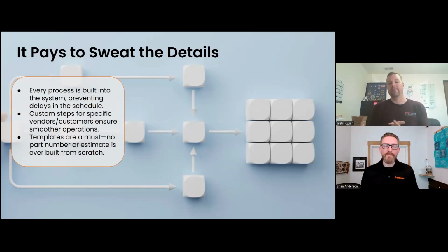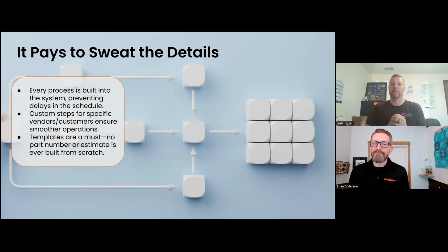But what that created for us was that work stoppage. So now we have those custom steps for this customer that right after we receive material, which is a line item on every work order, it's check for ultrasonic inspection cert on everything. And there's a big note: do not proceed past this step until it's completed.